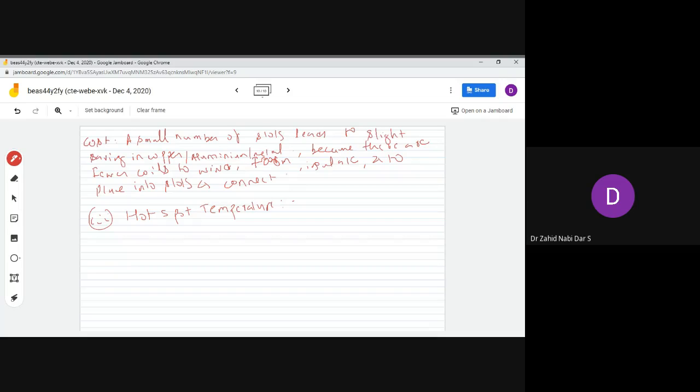If they are placed one after another, there is no air gap in between, so there is lesser space for air to circulate through. This gives rise to high internal temperature at those spots, resulting in hot spots. We have to be careful while selecting the suitable number of armature slots for the hotspot temperature.